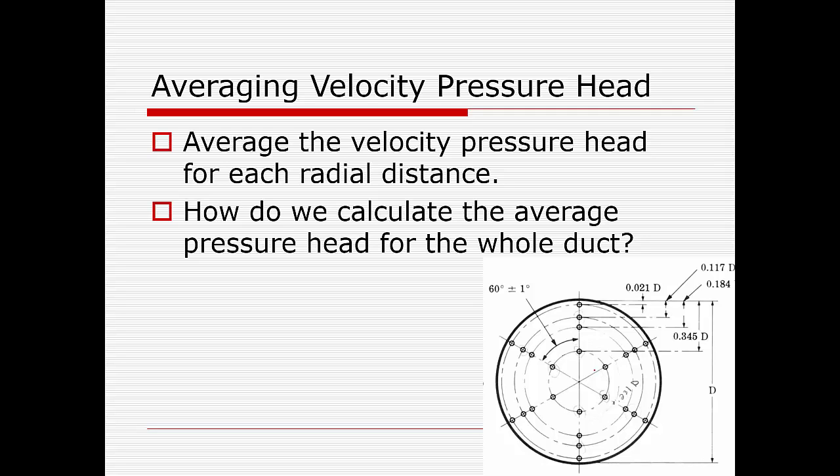Probably not. We cannot. Why? The system is designed for a laminar flow. We had a flow straightener and other stuff. So inside a duct tube under laminar flow, the velocity is like this, right? It's parabolic, right? The flow profile is parabolic for a laminar flow, right?